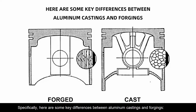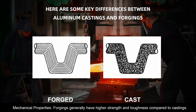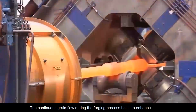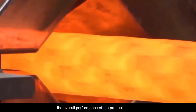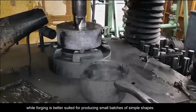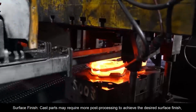Specifically, here are some key differences between aluminum castings and forgings. Mechanical properties: forgings generally have higher strength and toughness compared to castings. The continuous grain flow during the forging process helps to enhance the overall performance of the product. Production cost: casting is more economical for mass production of complex shapes, while forging is better suited for producing small batches of simple shapes. Surface finish: